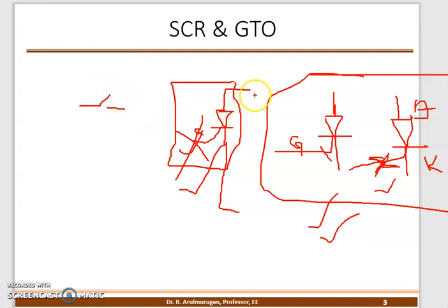Here I am going to give the power supply. I will apply an AC power supply, because AC consists of a positive magnitude and a negative magnitude, which interchange. The first half cycle is the phase with respect to neutral, and the second half cycle is the negative with respect to neutral. Shall I connect the switch directly to the source? No. Why? When the switch is closed, the source would be short circuited.